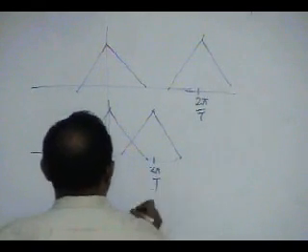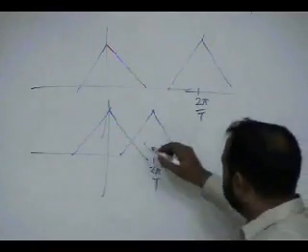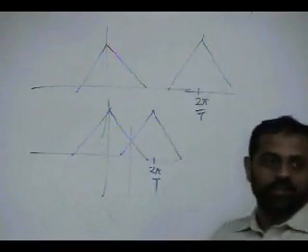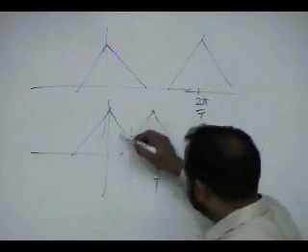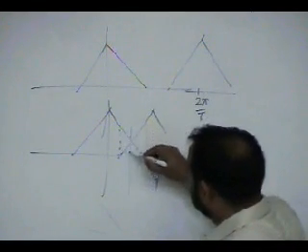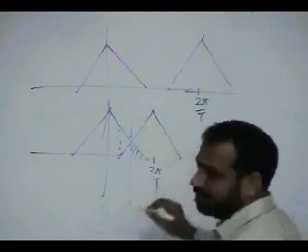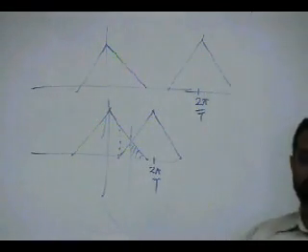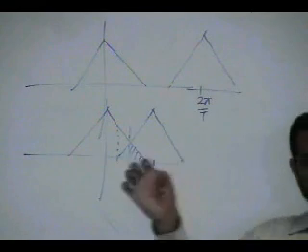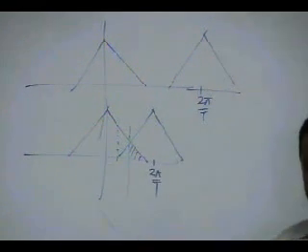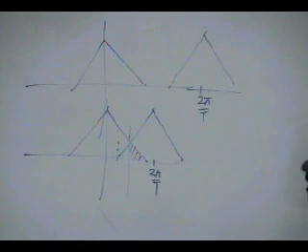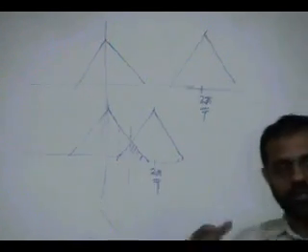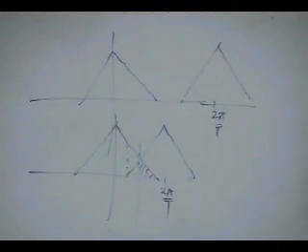Aliasing is that the part which is not obeying will go back and corrupt other frequencies as well. Not only that you will lose this part, this is one issue, that if you don't sample fast enough you will lose the high frequencies. That may be okay, but the problem is that that part will alias back and corrupt the same amount of frequencies in your signal. Okay?